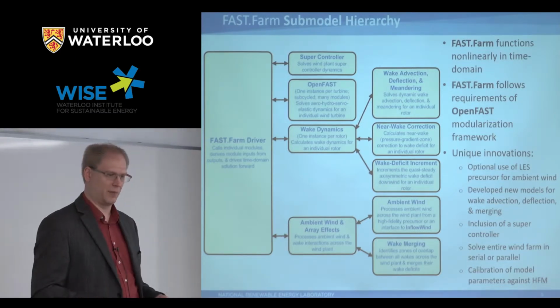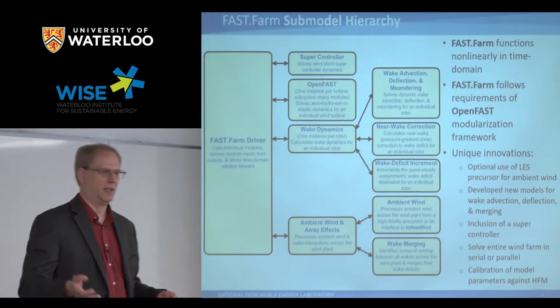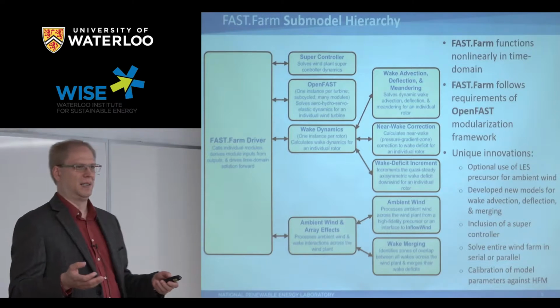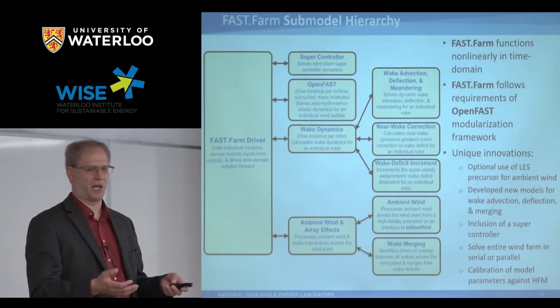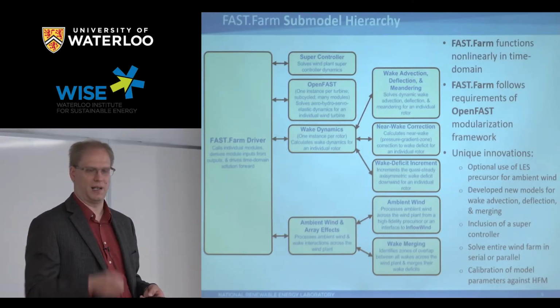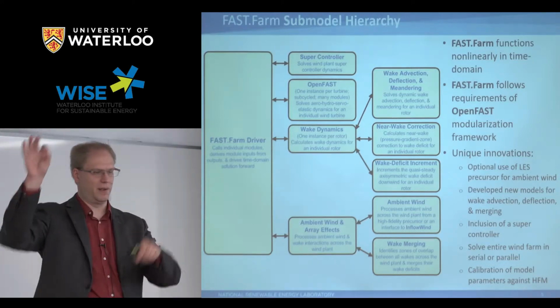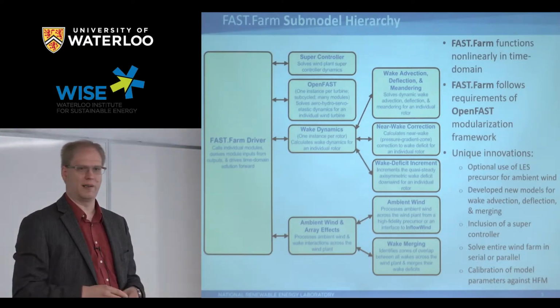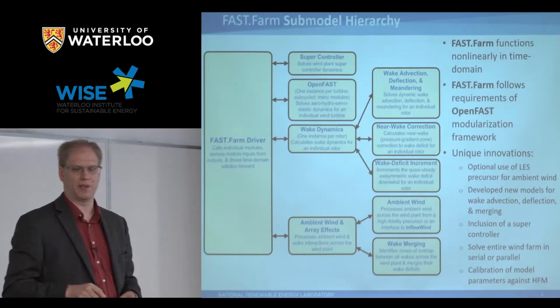The other option is a more synthetic approach. If you run FAST or BLADED, you're probably familiar with TurbSim or the Mann model. These are synthetic in the sense that we construct turbulent fields based on basic boundary conditions like power spectra of the wind and various components of the wind, coherence, how the wind is coherent across space, and how the UVW components of the wind are correlated with each other.